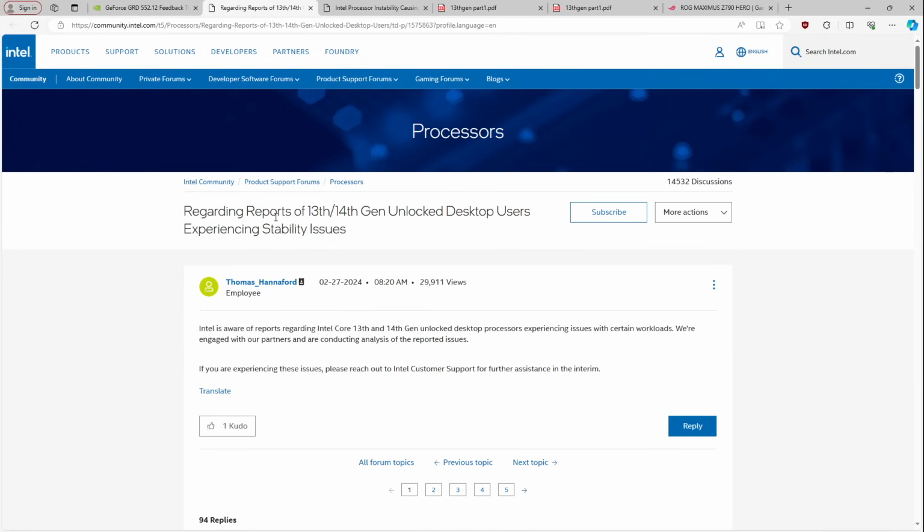My theory as to why it crashes in Cinebench and not in Prime95 small FFTs is that when it's thermal throttling at 100 degrees Celsius, Prime95 runs at about 5 gigahertz, whereas Cinebench runs at about 5.4 gigahertz. So Cinebench crashes because at 5.4 gigahertz and 100 degrees, it's not getting enough voltage, while Prime95 at 100 degrees and 5 gigahertz is getting enough voltage.